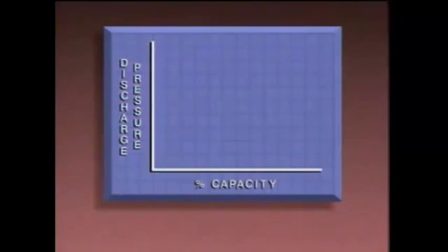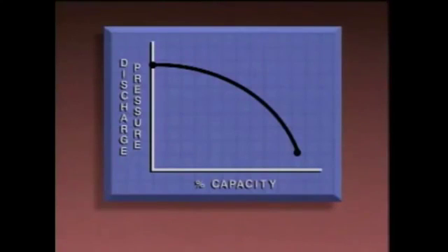If the pump is running and the control valve is fully closed, the discharge pressure is at its maximum value for the pump's speed, while the flow rate is 0. As the valve opens, the flow rate increases and the discharge pressure decreases. When the valve is fully open, the flow rate is at its maximum value, while the discharge pressure is at its minimum value. The curve that's formed on the graph is sometimes called a pump characteristic curve. Basically, it provides a way to see how a pump's discharge pressure is affected by different flow conditions.